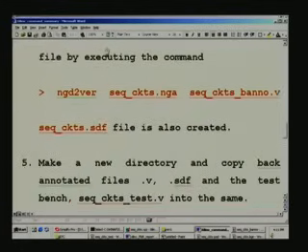So, here you have ngd2ver, ver stands for Verilog. So, you want to create a back annotated file which is nothing other than a .v file. So, also a Verilog file, and that file I have named like this, just to discriminate between the original design and the back annotation. In case you are putting all this in the same directory, suppose you had forgotten this, it will overwrite the original file. So, make it a habit to indicate, if this is too long you can say BA or whatever, and then it starts from the nga file which was created in the previous step, and that it takes as input and creates simply this here.